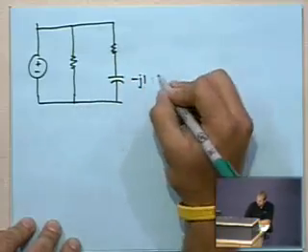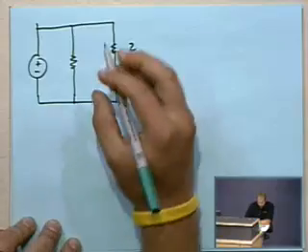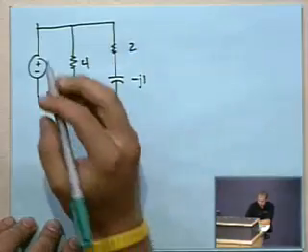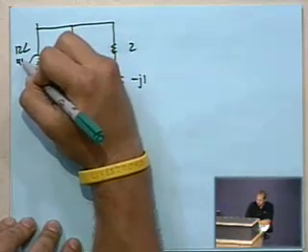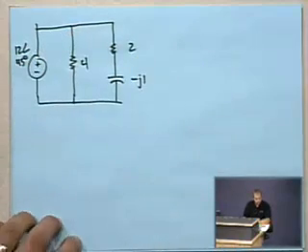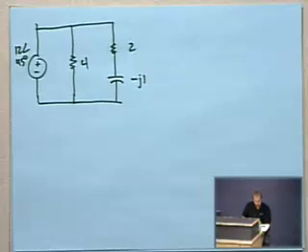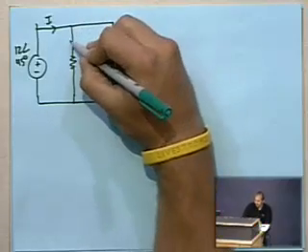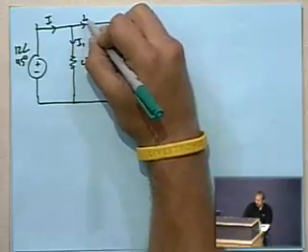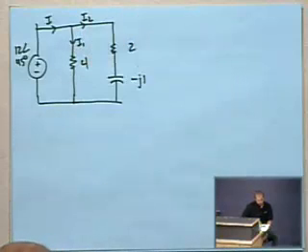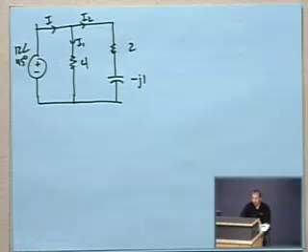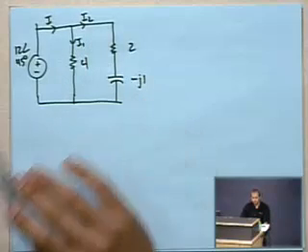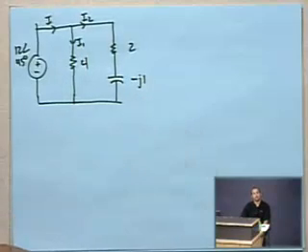So this is a negative J1 capacitor, a 2 ohm resistor, and a 4 ohm resistor. This voltage source is 12 at an angle of 45 degrees. And I guess as much for convenience sake, you can say here we generate some initial current I, and there's I1 and I2. As we start thinking about what are the powers that are being absorbed by the resistors and capacitors and whatnot, we'll use those to keep the current straight as we start plugging it into the average power formula.